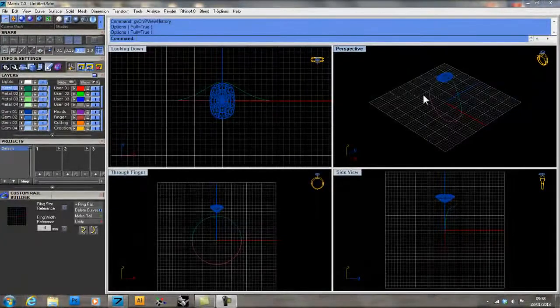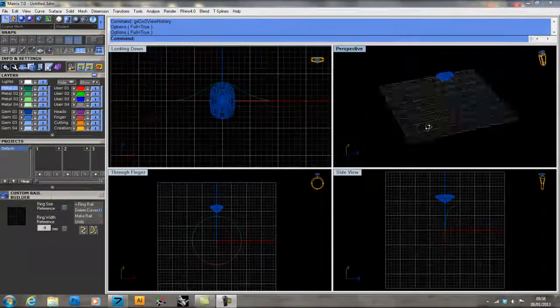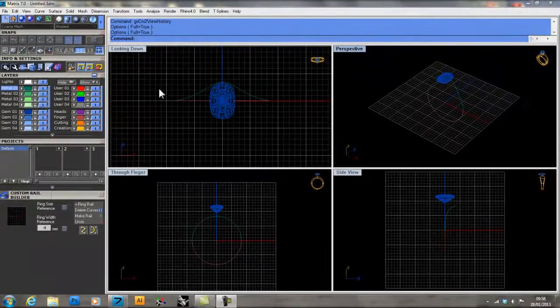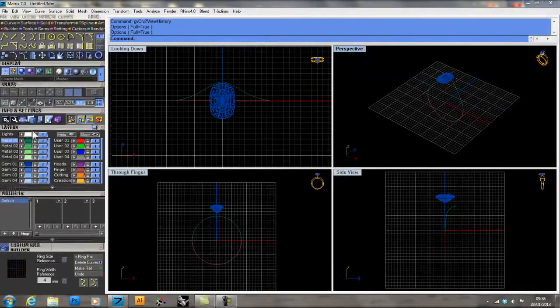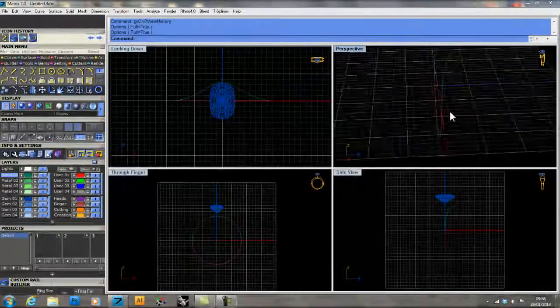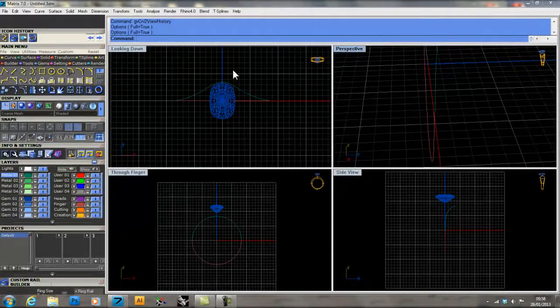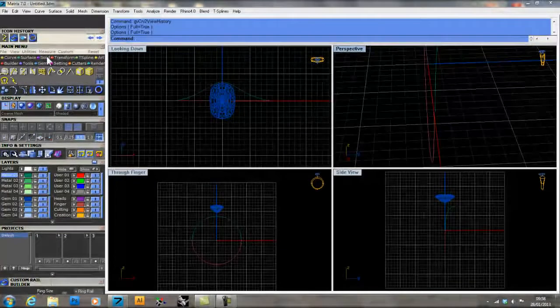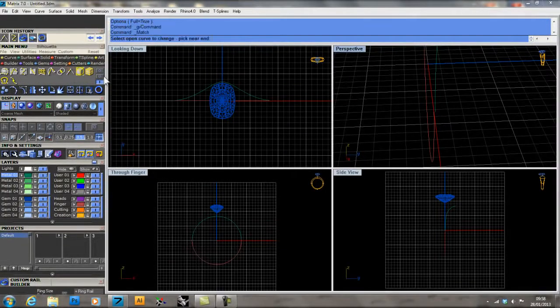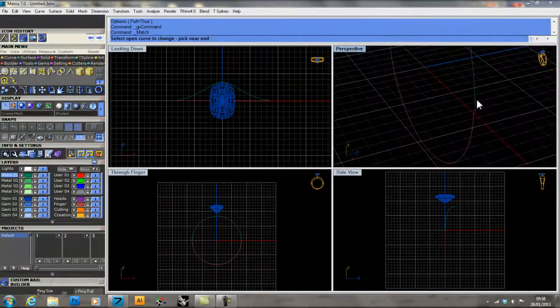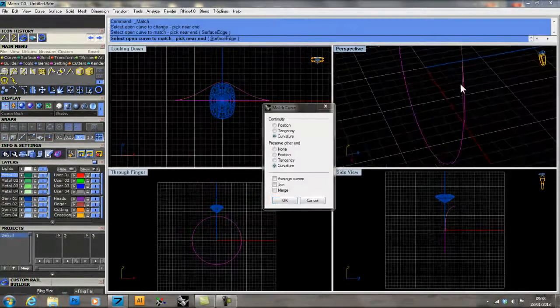This is one way in which the way I do this is different from GemVision's standard method. And I find this is rather important to make sure the shape is going to be clean in its final result. So what I will do first is I'm going to actually take the top and bottom and reconcile them. I'll do so with the command in the Curve menu in the third tier called Match. I'll select the end I want to match from and the target end I want to match to. And this will force the two curves to combine together.